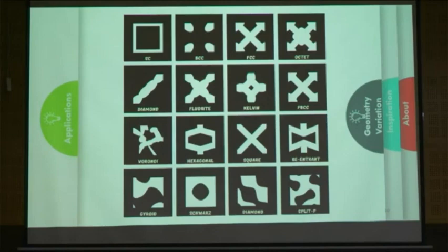Frankly speaking, since we don't have a device to measure roughness, I can't give numbers, but it is a very rough surface. Using post-processing we have improved the surface. Powder stays stuck to the lattice, giving a higher roughness, and we applied sandblasting.